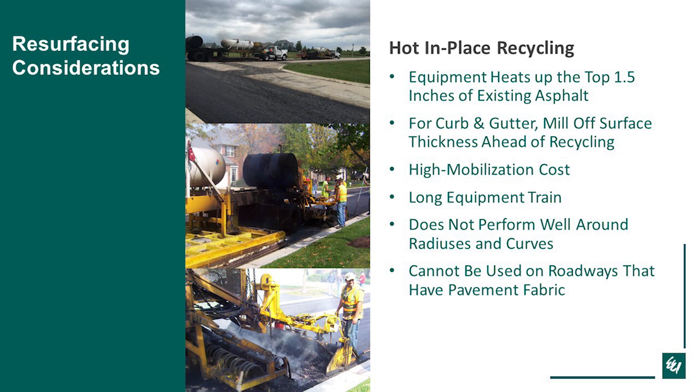There's a long equipment train. It's usually about 40 feet with the unit that heats the asphalt back up, the scarifying unit, and then there's a unit that adds in an asphalt rejuvenator back in and paves it back down. So with that,